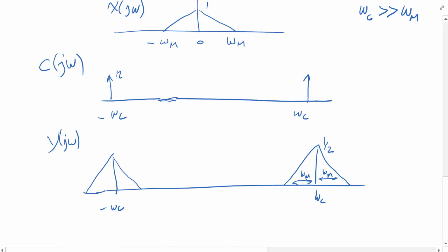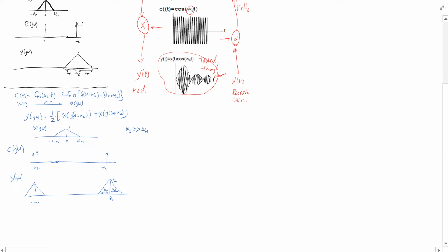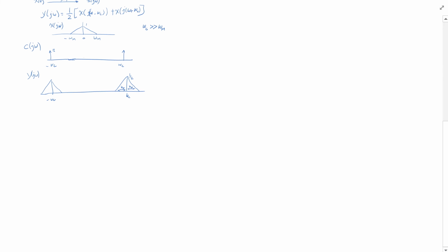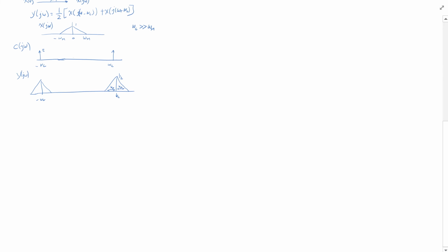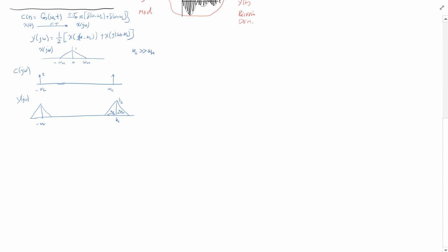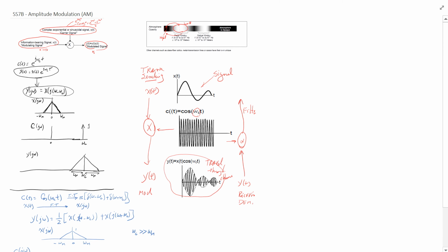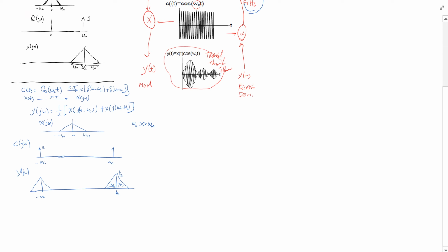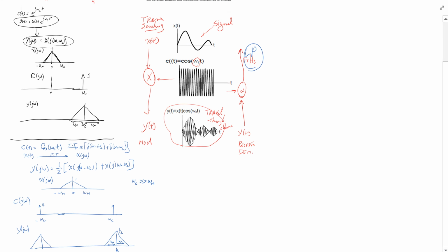Now the beauty is, if I run it one more time through this process, which I just mentioned briefly in the last case we had for demodulation, this 2 will move by ω_c this way and that way, back, and the original signal will get back out if you put a filter through it. There is a need for a low-pass filter here to clean the signal back out. So that's basically modulation and demodulation.